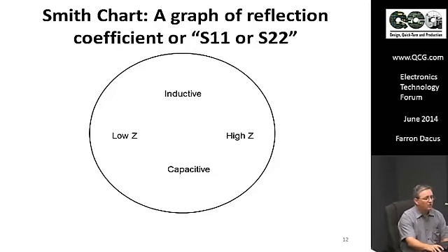So to keep in mind on the Smith chart, it's normally got these odd looking lines and circles. It's filled up with those when you see one, and it kind of hides the fact that there's some regions here that are very helpful to keep in mind. So the center of the Smith chart is normally 50 ohms, though it could be something different. 50 ohms is standard practice.